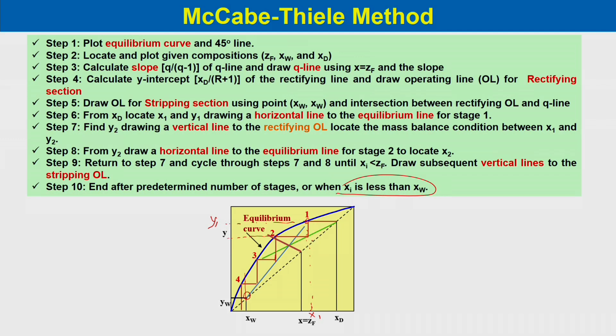Please note that while drawing the staircase arrangement or the stages graphically, the shifting from the rectifying section operating line to the stripping section operating line will happen at the feed line. So, you can see this is the intersection, this is the feed line. So, this plate 2 over here is the feed plate.